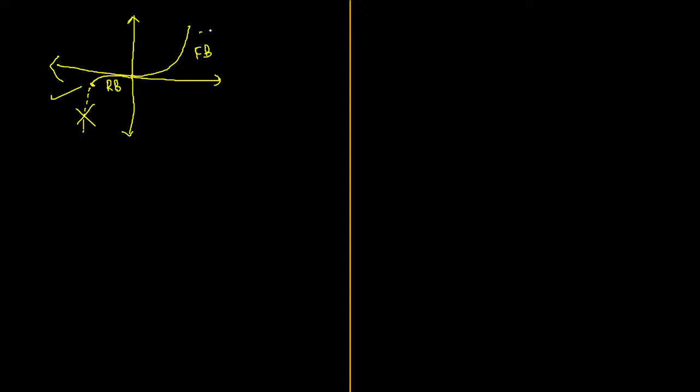What is this curve? This curve exactly indicates the current flow through the diode. See, this is voltage versus current. In the forward bias I keep on increasing the voltage. Initially from 0, when we inject some amount of positive voltage, there is no current flow. If you observe, the initial current value is very small, approximately equal to 0.